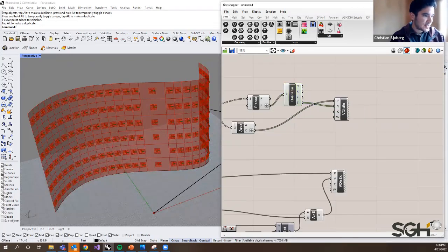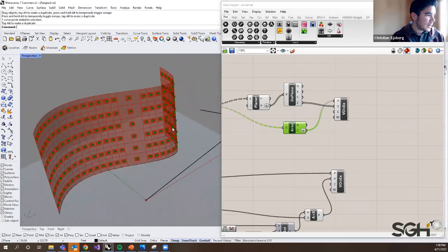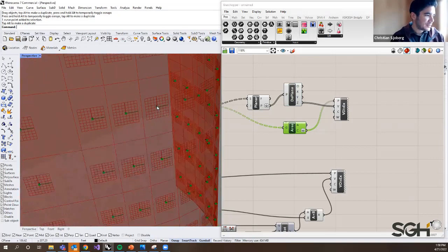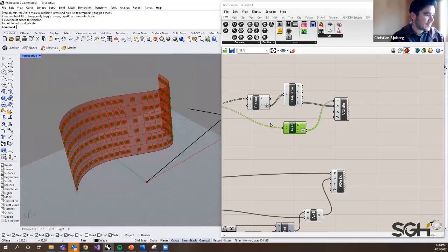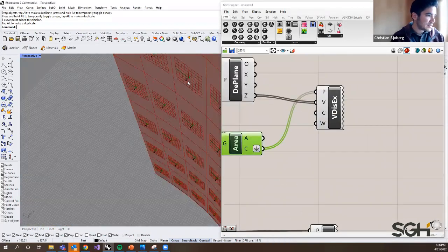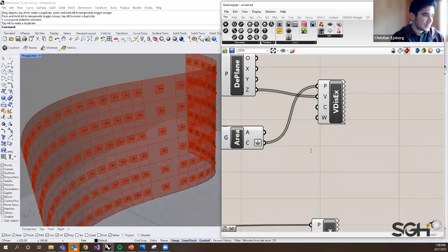Okay, so a couple more steps and then we'll have what we need here. So basically we need to take all these little vectors and we need to reflect our sun angle off of those, right? I'm noticing that just the way we drew this line, they're all facing the wrong direction. I kind of want them facing out the other direction. So I'm just going to reverse those as well, reverse that vector.